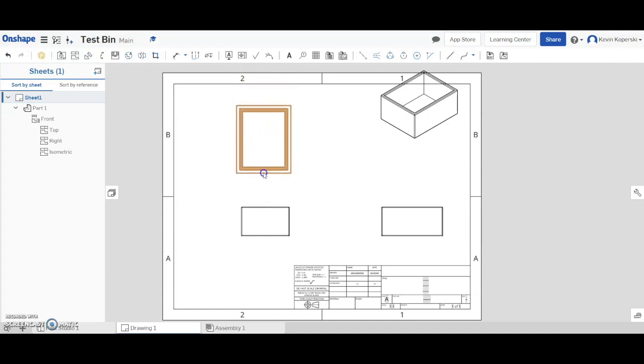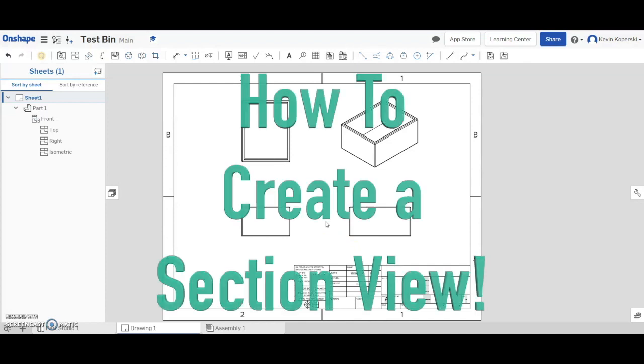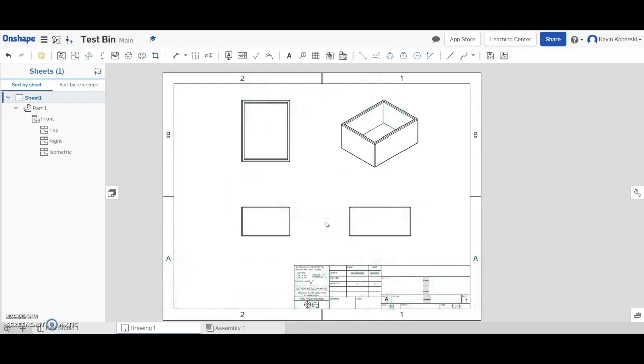And once I do that, now I can drag parts in, and I'm looking at my orientation of all of the pieces. I would definitely make some changes here because this, as my front view, it's okay. This is my top view is okay. Probably with most of your bins, you're going to want a section view. You're going to want to be able to cut the thing in half so that you can see the thickness, especially since you guys all were supposed to do a shell feature. You should be able to see the thickness of that shell and what the cutout of that area looks like.